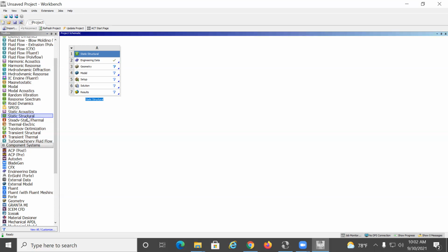So I repeat, we're going to need material properties. We're going to need a geometry. We're going to need a mesh. We're going to need boundary conditions. We're going to need loads. These are all inputs. Once I have my main inputs, I can assemble the global stiffness equation and see if there is a solution. So I go to a solution.